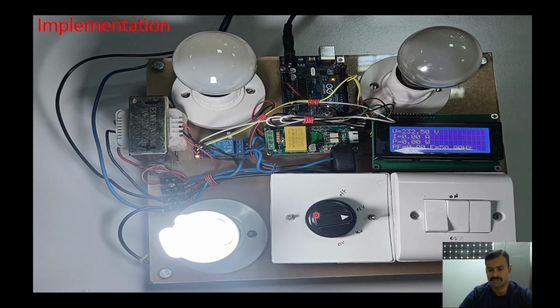So this selector switch, we are going to see here the off position, normal voltage condition, under voltage condition, and over voltage condition. I have three switches to operate these three different loads. Based on the switch operating condition, these loads will be getting on, and the transformer which I used here is for getting the different voltage levels. The relay module is here to turn on or turn off the loads under normal and abnormal conditions. This is my energy sensor, and this is my current coil. So let us see how it works.